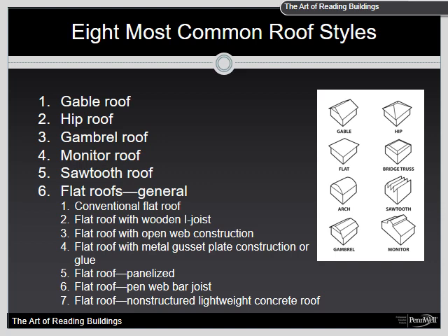Hazards. Metal exposed to fire or sufficient heat, between 800 and 1000 degrees Fahrenheit for steel, will expand, twist, and likely fail. The time necessary for a roof collapse is a major concern when the entire roof is composed of metal. An additional hazard is the travel of fire between multiple layers of tar, paper, insulation material, or the corrugated metal decking.